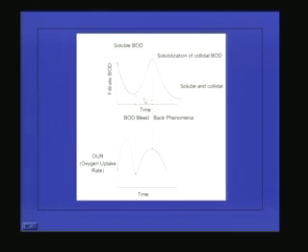But if colloidal particles are there, it will go like this, and meanwhile the microorganisms will be hydrolyzing the colloidal particles and making them soluble. So again the soluble BOD will be increasing, then again it will be decreasing. This is the pattern of filtrate BOD or the soluble BOD.